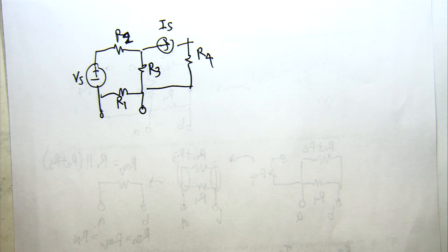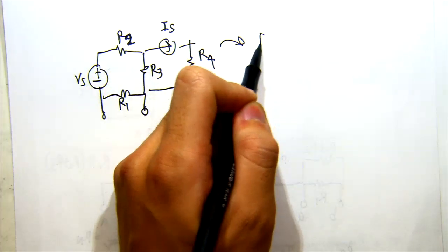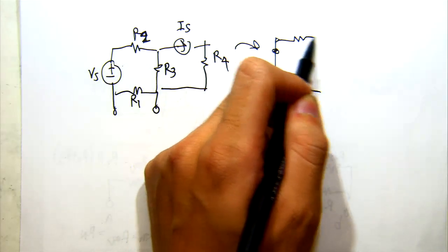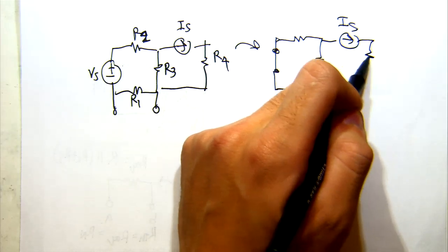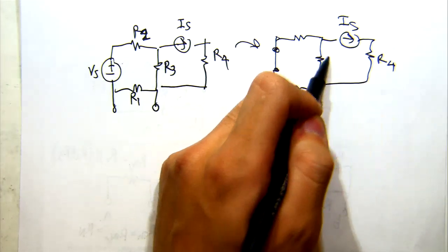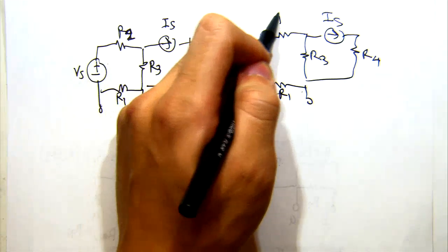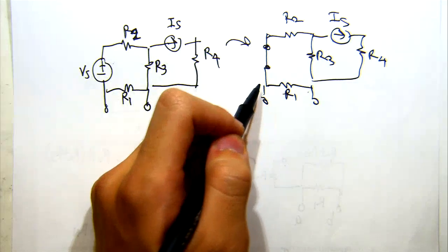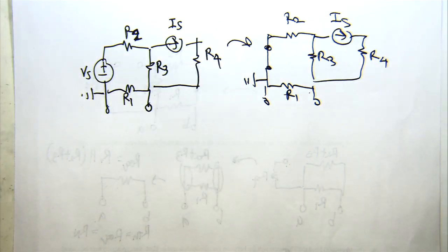Okay, cool. So if we turn off the voltage source this time and leave only the current source on, then we're going to expect to see a short in the place of the voltage source. And then we'll have all these other resistors as before. And then here we'll have this current source. And you can fill everything in. So in this case, it doesn't look like there's a nice analysis method I can use like before. But I'm going to maintain the same location for ground.